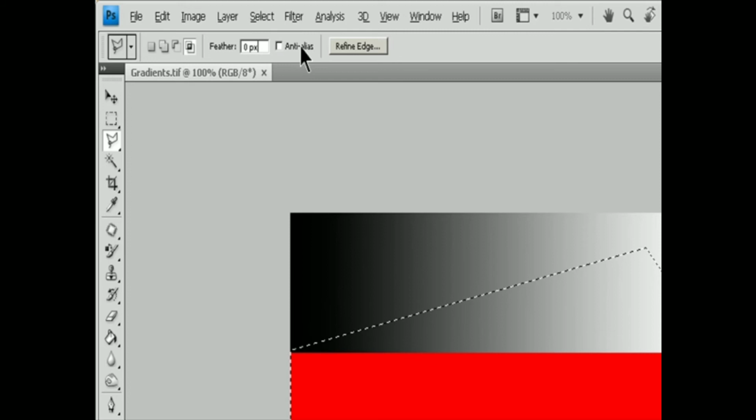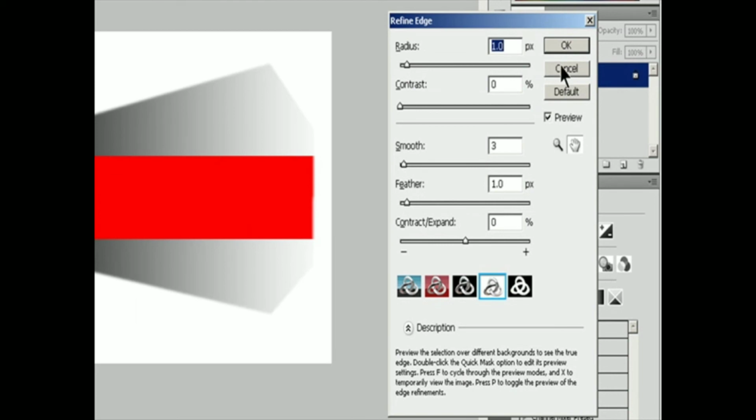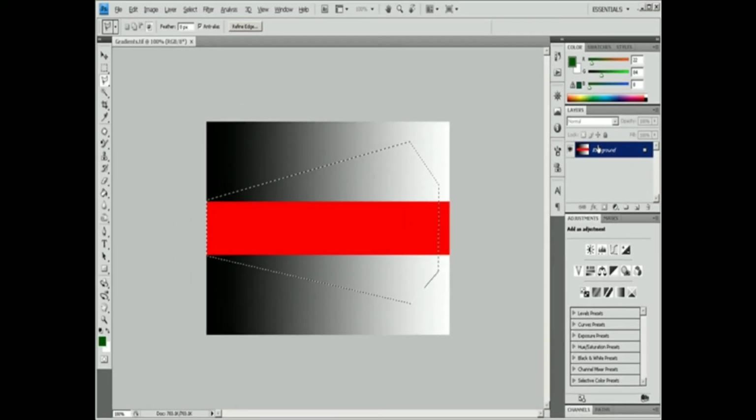To draw a straight segment, position the pointer where you want the first straight segment to end and click. Continue clicking to set endpoints for subsequent segments. To draw a straight line at a multiple of 45 degrees, hold down Shift as you move to click the next segment. To draw a freehand segment, hold down Alt in Windows or Option in macOS and drag. When you finish, release Alt or Option and the mouse button. To erase recently drawn segments, press the Delete key.